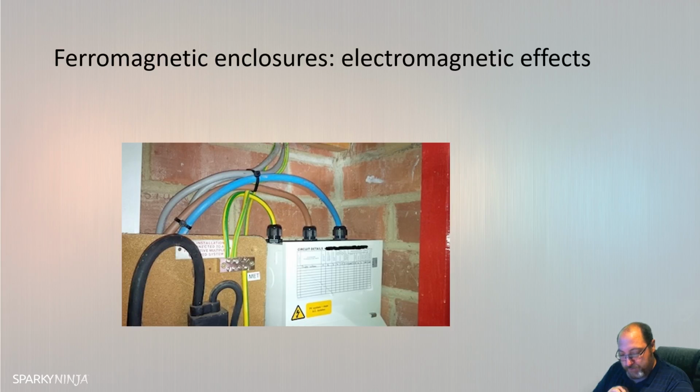Okay, I've seen that as a question actually, asking which cable can go on its own through a ferromagnetic enclosure, and it's the additional earth, like on an armour or something like that. All the live conductors and the neutrals and everything, as it says there, should go through the one point. This is all because of the theory of the eddy currents that can circulate when you have this kind of thing.